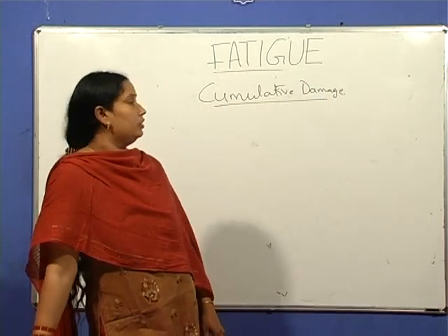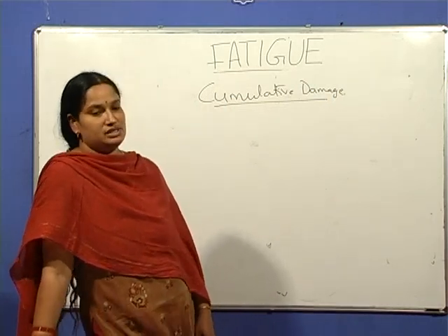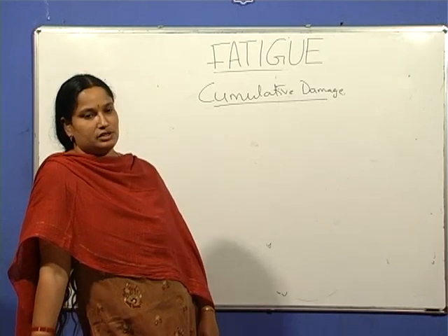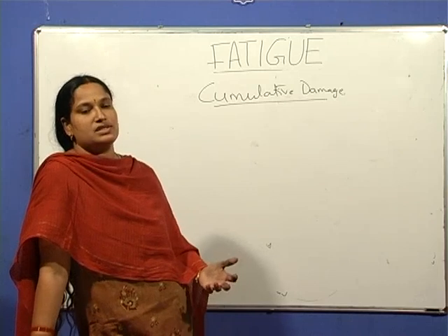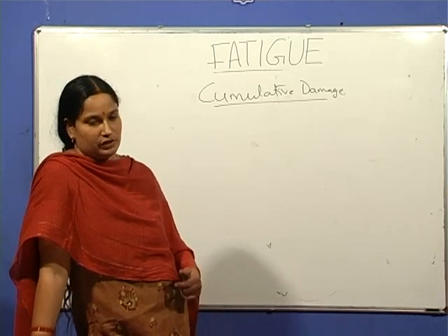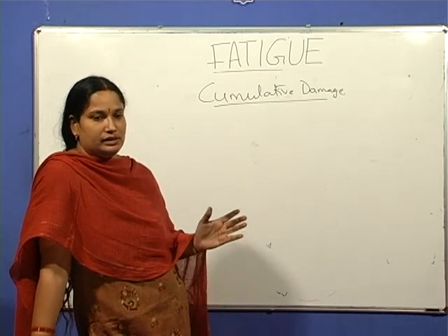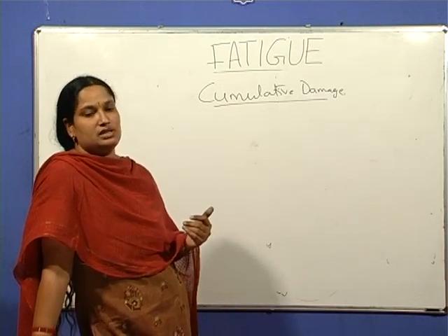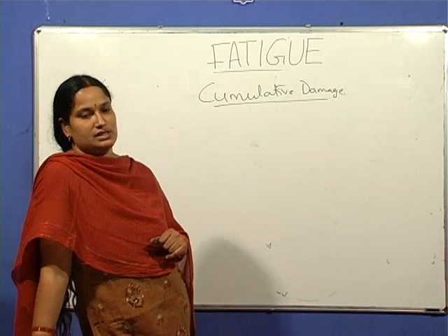In the case of cumulative damage, fatigue tests are conducted for simple conditions, by maintaining constant amplitude and constant frequency.